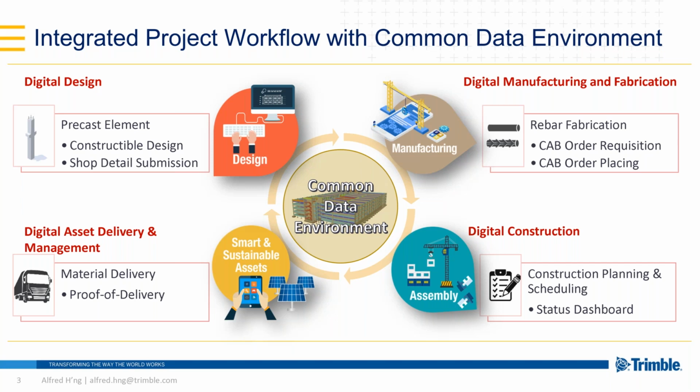And next, we look into streamlining the rebar fabrication ordering process. Rebar data is extracted automatically from BIM models, uploaded to the Common Data Environment, where ordering details can be generated for fabrication services.